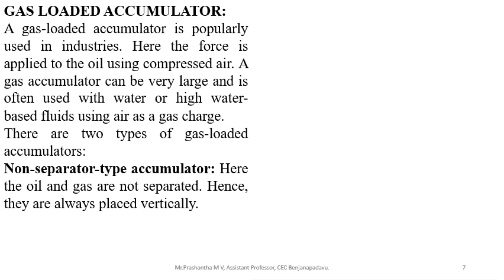The compressibility of gases accounts for the storage of potential energy. This energy forces the oil out of the accumulator when the gas expands due to the reduction of system pressure or when the fluid is supplied to the machinery or system.